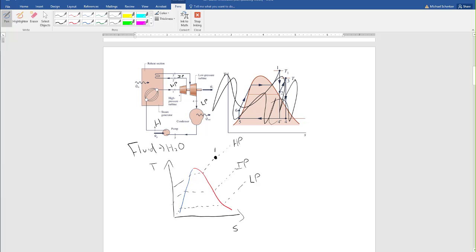Now, I have isentropic efficiencies in this case, so I'm going to draw this imaginary vertical line down from state 1 to state 2s. This gray line, that process doesn't really happen, but we can pretend it happens. And then I'm probably exaggerating this to get to the real state 2, so now this goes down and to the right.